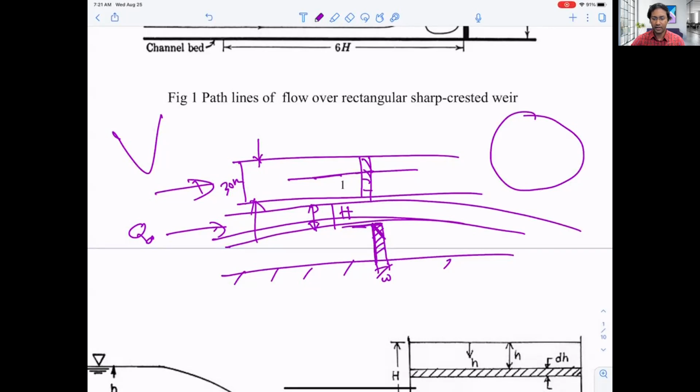So far we have seen that our efficiency, or the coefficient of discharge, is increasing from one experiment to the next, right? And we'll see that for the V notch, when flow occurs this way, it will be the most efficient device to measure flow, and that device is very useful if you vary the flow rate from the lower limit to the upper limit. So it can measure flow for a wide range of flow rates. So that's what we'll do, okay?